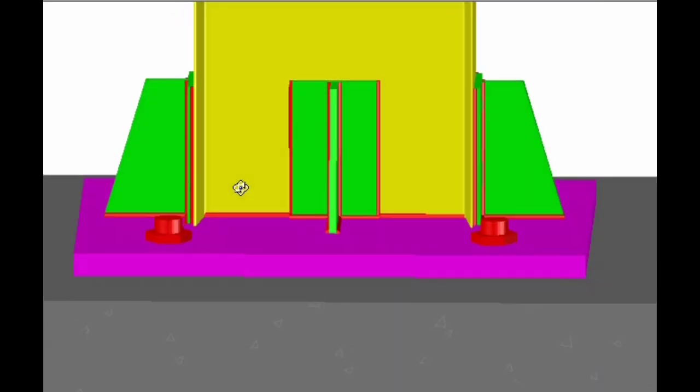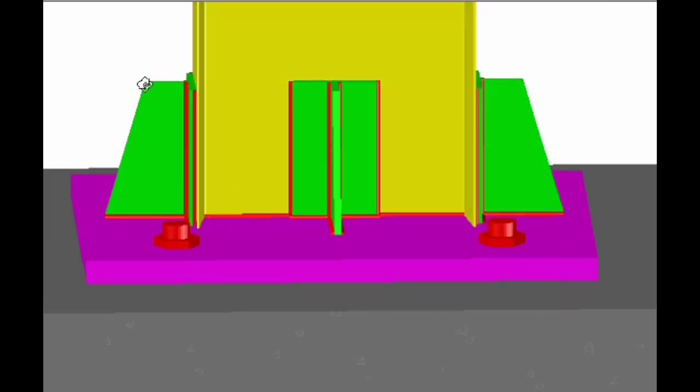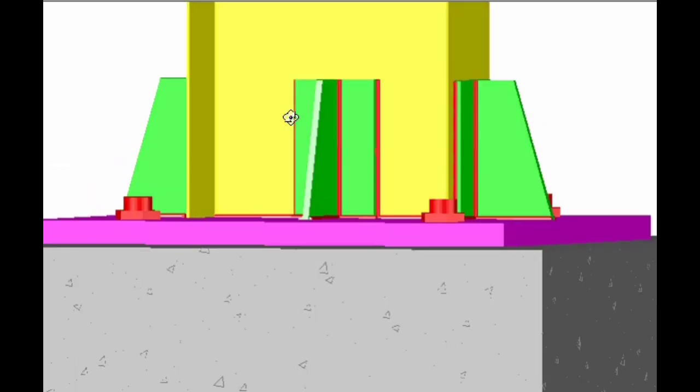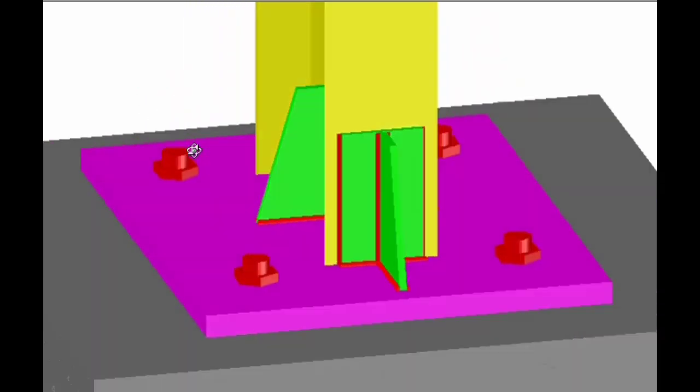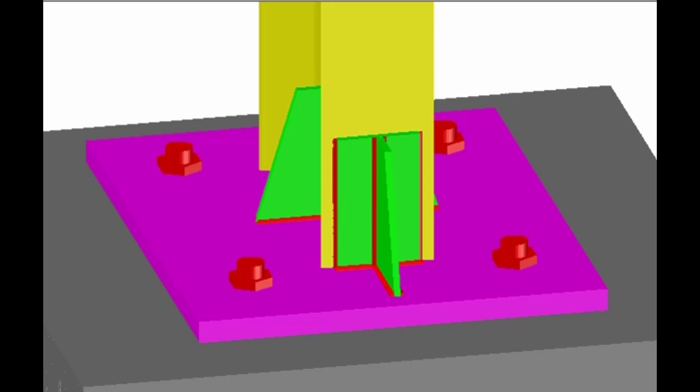And from the architectural point of view, we have tapered this, cut the section plates like this. It's only from the architectural point of view. I'll show you the plan of this one. Just have a look at the plan. This is a plan where you can see the I section, the additional plates here, and these are the stiffeners. Where the length has been increased, you're going to do the welding like this.